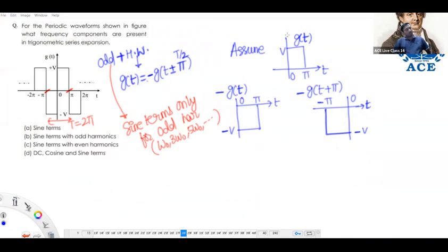But if you make a direct observation, what is your feeling? Only odd symmetry means immediately you may take the first option. So be careful. Don't lose this simple question because of your unnecessary emotions. In the options, if the word odd harmonic is used, it means there is a possibility of half wave symmetry. Even and odd, just by looking at the graph, we can decide. Half wave is taking some time for us.